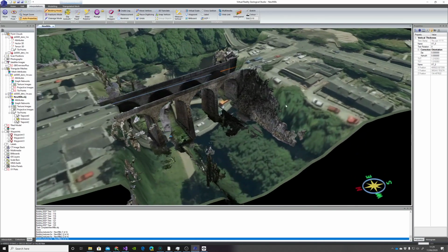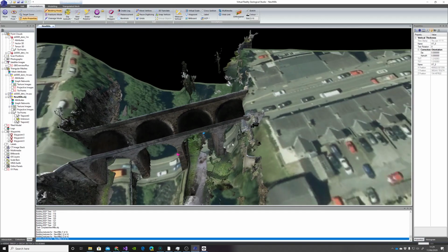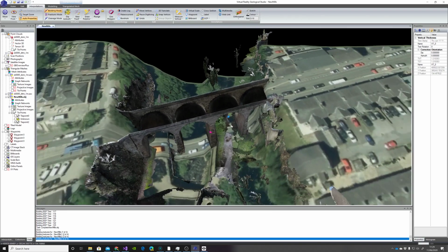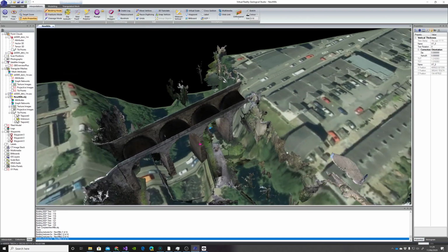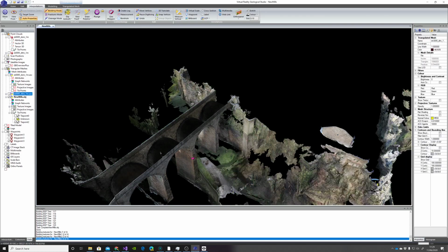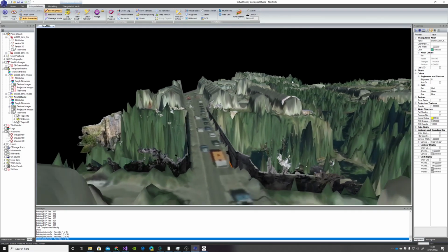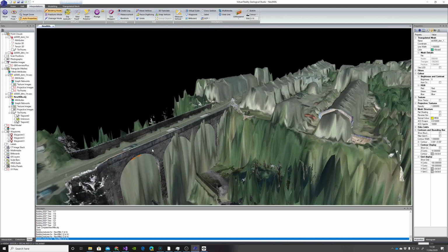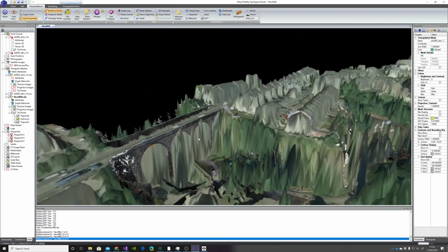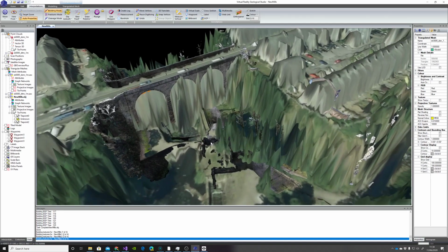So that shows you how you can get a fairly reasonable fit between your structure from motion data and elevation data if you haven't got any georeferencing information at all. We could carry on for a bit longer and do a few more corrections. This is where our surface model is also quite useful, and looking at the surface model as well shows us that it lines up quite nicely with the data, giving us a fairly good confidence in the positioning.